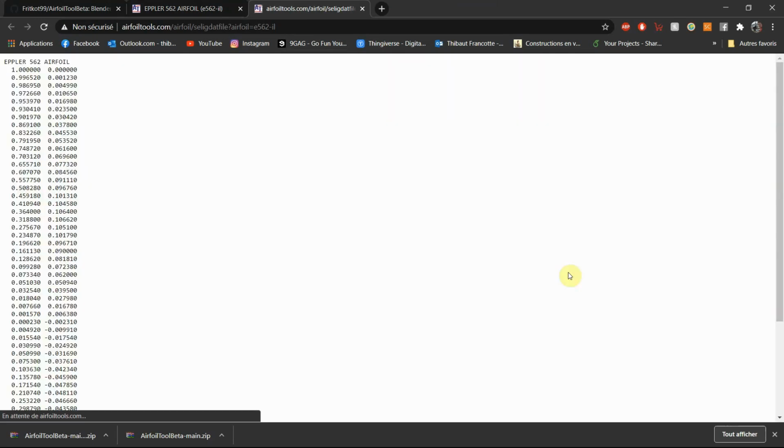However, be careful that in that case, if it's not a NACA or NASA airfoil, do delete the header here, because it could raise some errors. If it's NASA or NACA in the title, it should not make a problem. And also always check that the separators used here are a tab and not spaces or other weird things.